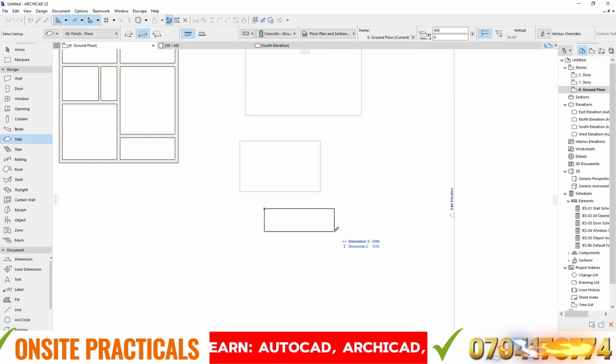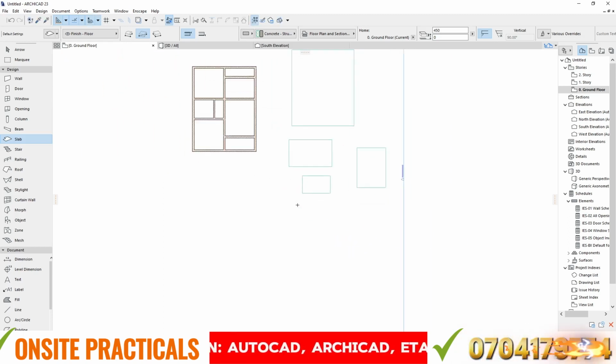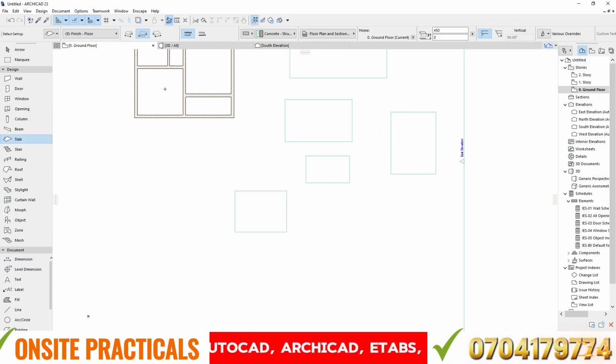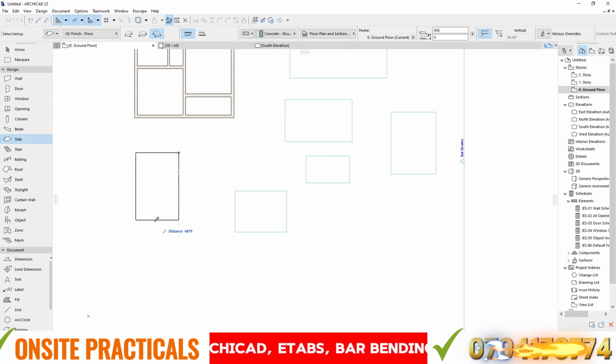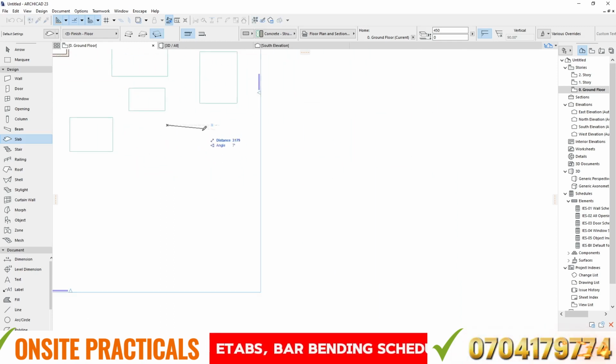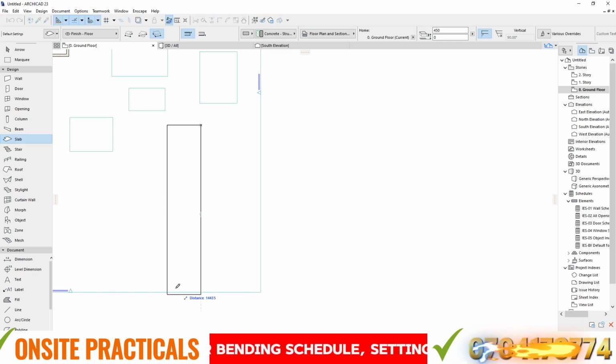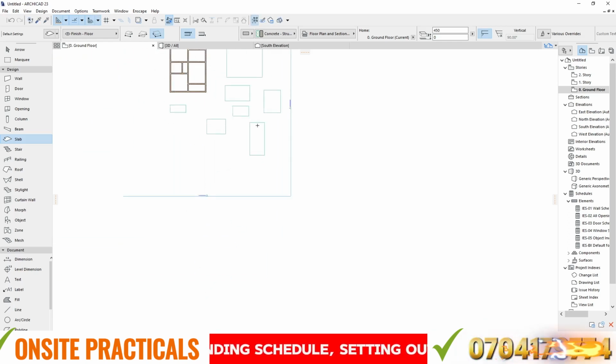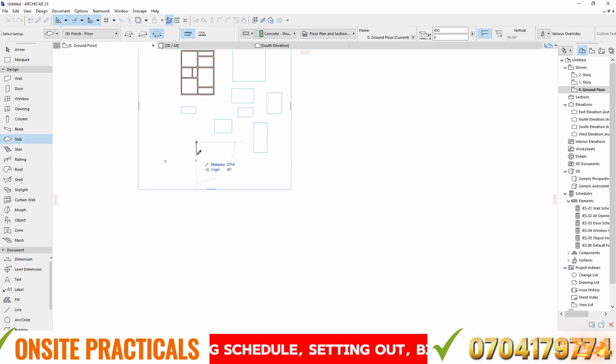So you can draw any shape that you want for that slab. And of course we have this one, rotated rectangular. I think mostly you would not really use this, but it's the same way we had for the wall: you determine one side and then you pull. For example, here I can say this is 3,000, and then I can pull this. Or I can say I want it to be 5,000 in this direction, and then I determine the size on this side.